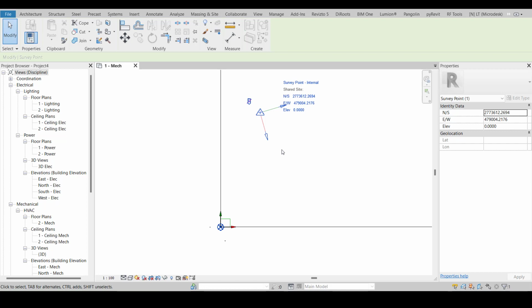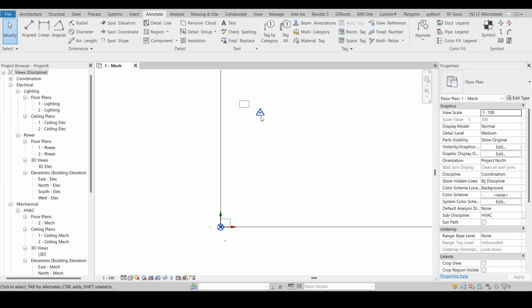If you don't use this, you are not going to get a big effect, but if you have the data, you can feed it and use it. Another thing is, if you put elevation here, you have to put the same elevation in all your linked files also. If you put height here and not in your linked file, then the elevations of the buildings will not match, even if the coordinates are matching. So that is another problem, and that's why you need to keep it.